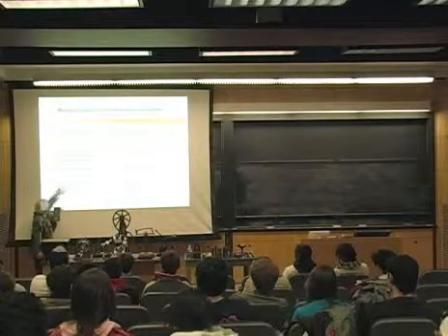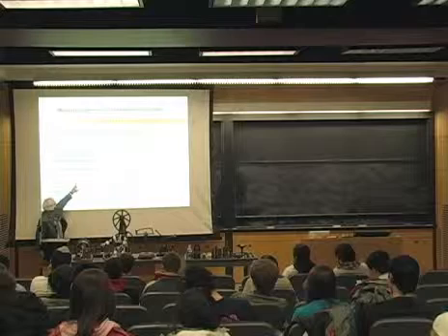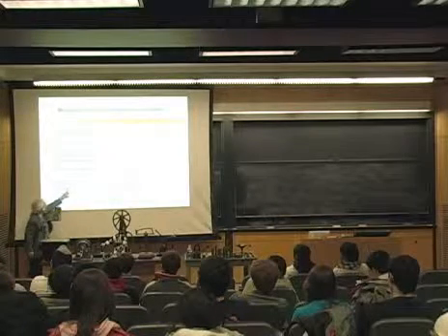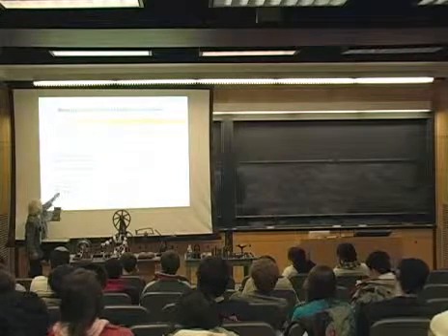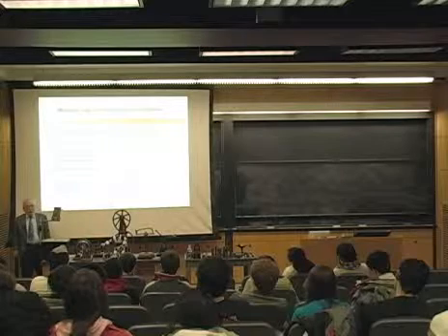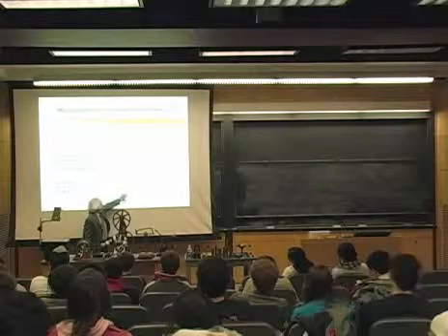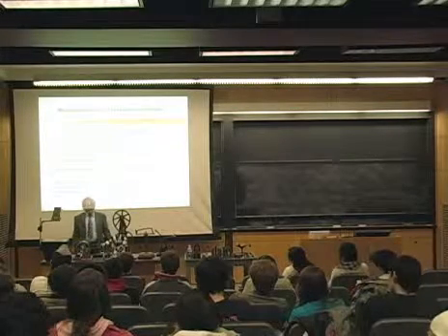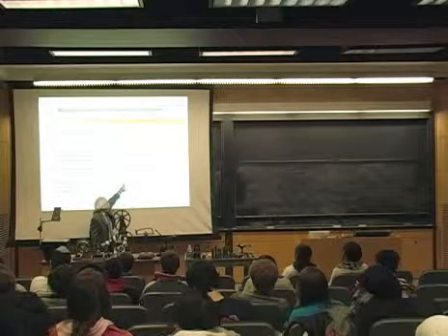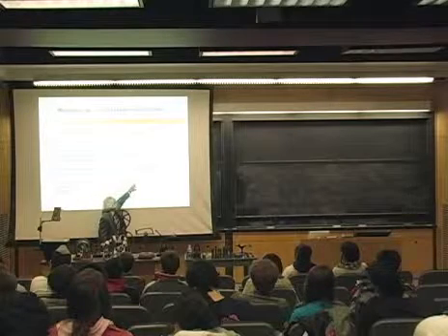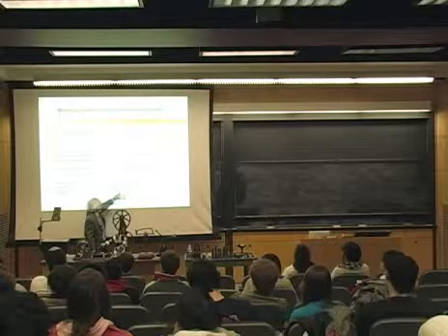In other words, if you have 4 links and you want 1 degree of freedom, you have 4 joints. If you have 6 links, you have 7 joints. If you have 8 links, you have 10 joints. Now, there's no reason why you have to stick to 1 degree of freedom. For example, I could say I'm going to create a planar robot arm that has 3 degrees of freedom. All right? Well, if I put F equal to 3, if I have 4 links, I can have 3 joints. If I have 6 links, 6 joints, and 8 links and 9 joints.